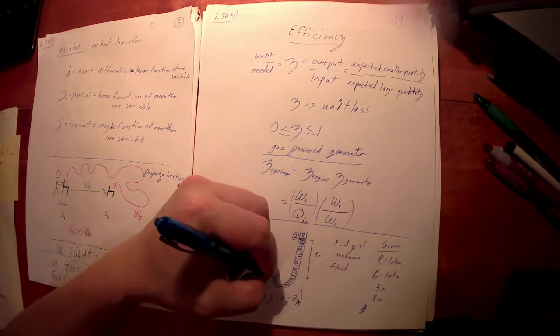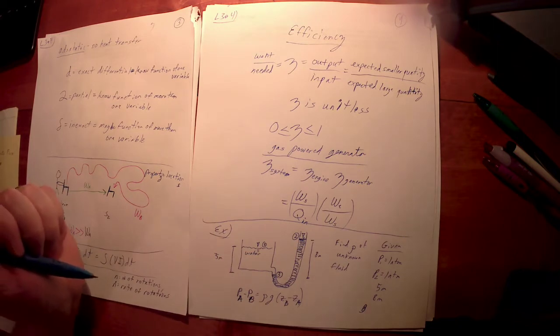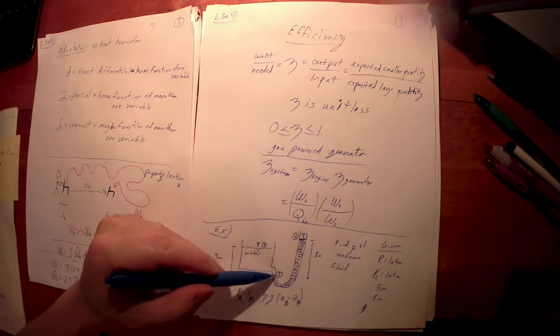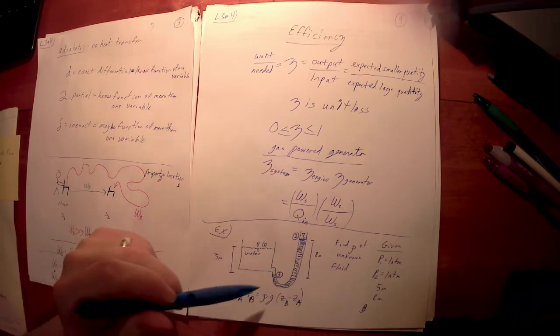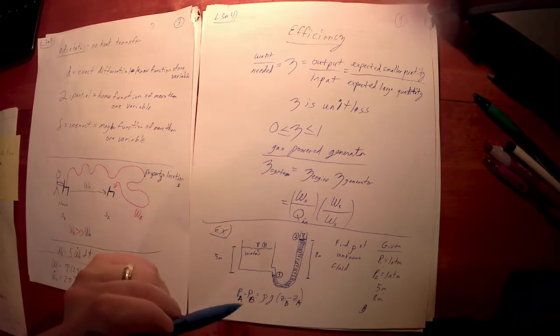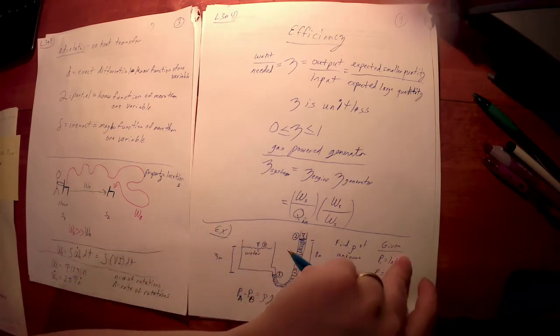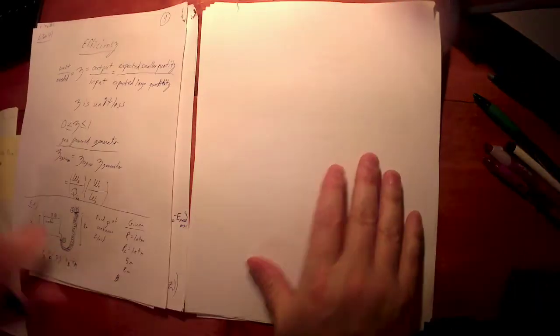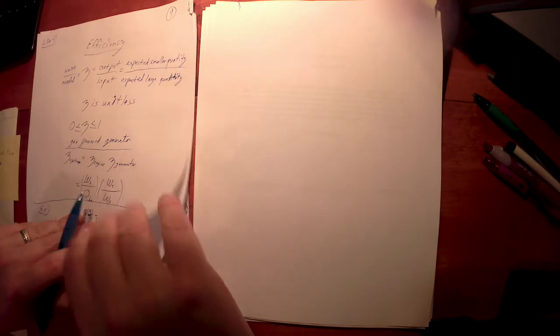In this case, I've got 3 surfaces here: surface 1, 2, and 3. I've got a fluid between 1 and 3, and a different fluid between 2 and 3. So I can only use this equation between one column of fluid, the way it's written. So I need 2 equations because I've got 2 columns of fluid.